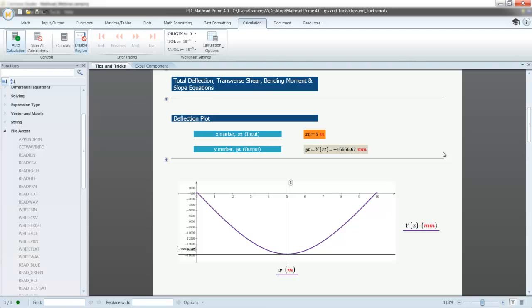So instead of editing one and the system recalculates the whole sheet for that new value, turn off all your calculations, edit all of the values, and then turn it on. Then it will recalculate with all of the new values, as opposed to one at a time, and you're waiting for that recalc after every input.